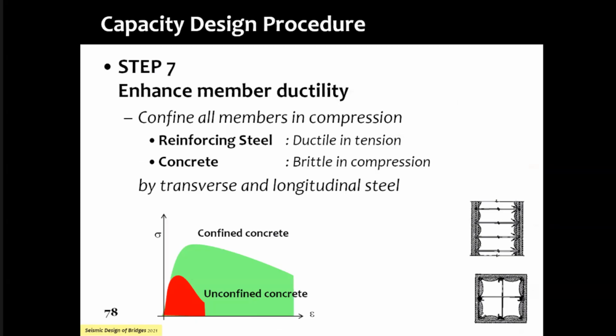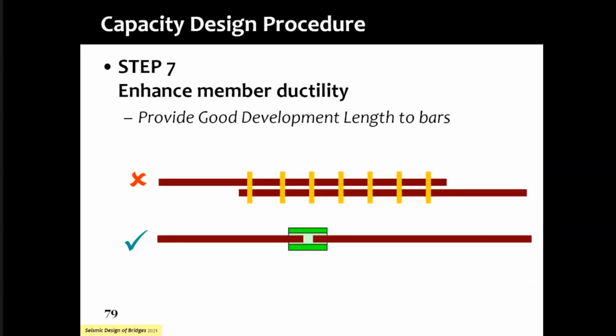Very good. Now we are saying enhance the ductility of these vertical members. How do we do that is where we are getting into a discussion. One item that you're looking at is that lapping is gone. That is not an acceptable solution for seismic design of bridges. Longitudinal members in a substructure cannot be lapped, cannot be relied upon with just lapping. And so is the story with transverse reinforcement. Lapping is not acceptable. I urge all of you to go back and look at your past drawings, and you will notice that that was one of the ways we were letting it go, but that is not acceptable anymore.